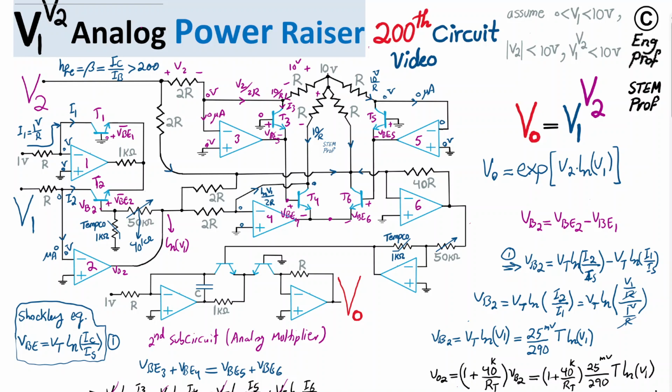So because again, via this OpAmp number 6, the virtual short because of negative feedback and proper bias is there. So 0 volt at positive terminal reflected as virtual ground at negative terminal as well. And as a result, we have just the 0 volt here, which then means we have this contribution, which is V2 divided by 2R as a current. And also we have this contribution coming here, this one.